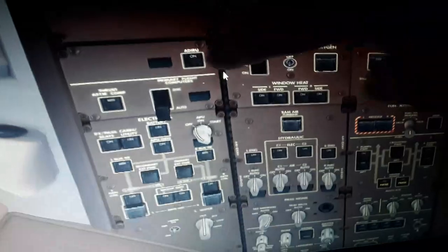So we have the ADIRU, the air data and inertial reference unit that displays and monitors the air data control system with the pitot static, the airspeed, the barometric altitude, the rate of climb and descent, the radio altitude, magnetic heading and track, the GPS information and inertial reference, and the attitude of the aircraft. We have the laser gyroscope of the aircraft that displays things like the acceleration and deceleration, and the heading. So very important controller, the ADIRU, the air data and inertial reference unit. We also have the flight control computers.